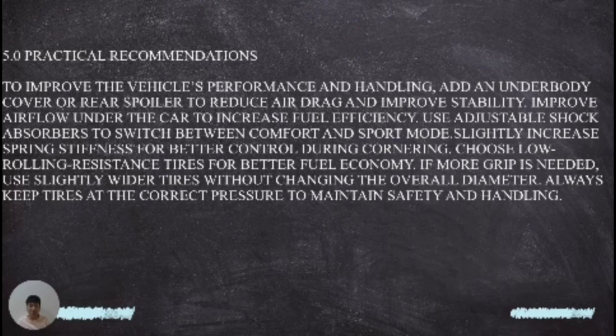Next is about practical recommendations. Based on the findings, here are some practical recommendations to improve the vehicle performance and handling. Add an underbody cover or rear spoiler to reduce air drag and improve stability. Improve airflow under the car for better fuel efficiency. Use adjustable shock absorbers to switch between comfort and sport mode. Slightly increase spring stiffness for better control when cornering.